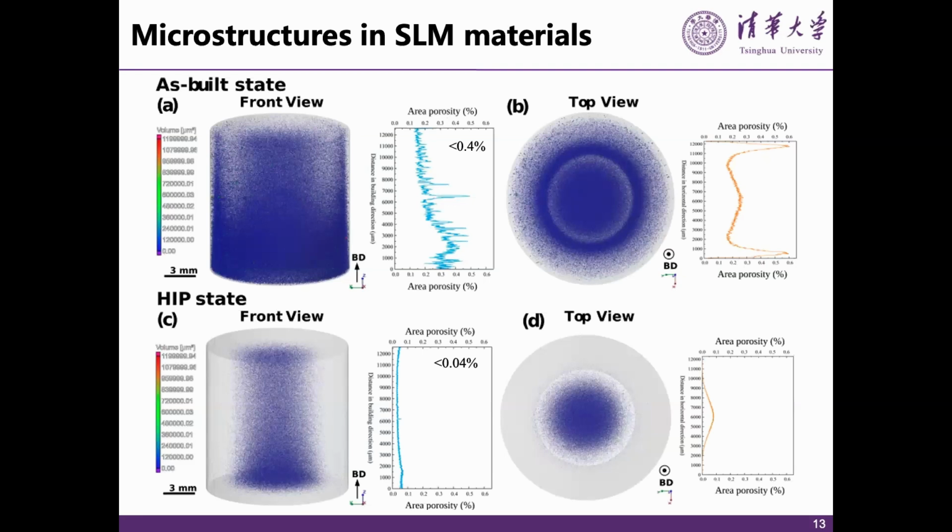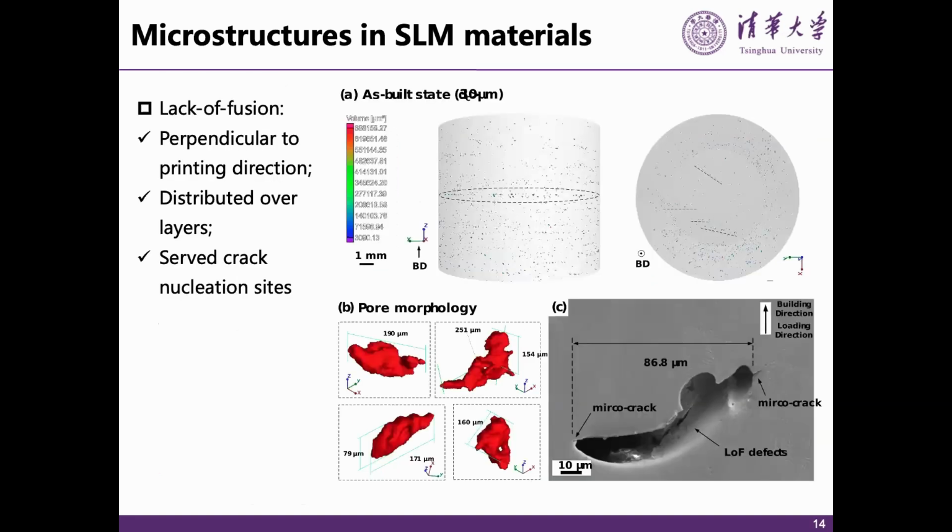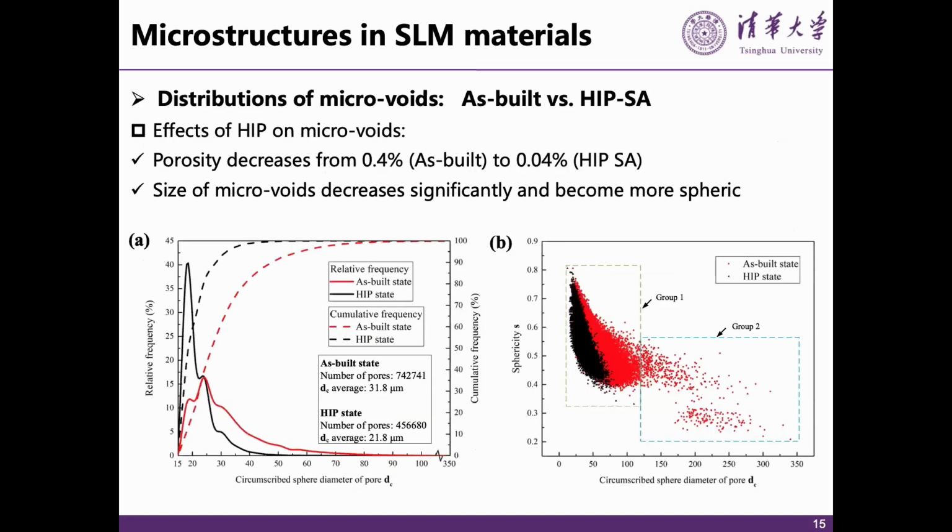The material of course contains much porosity. After HIP, we see the surface becomes clear due to the high pressure, but in the center we still have this kind of porosity and voids. How to quantify the effect of voids is still an open issue. The reason is what we found: the yield stress seems very similar compared to Inconel 718, but the fracture strain is much smaller, right? Less than 50% compared to Inconel 718. Therefore, how to quantify the effect is still the issue. That is a topic we will continue investigating.